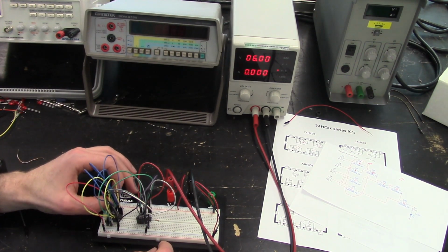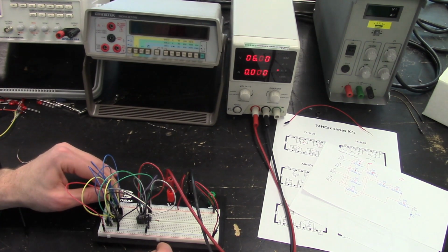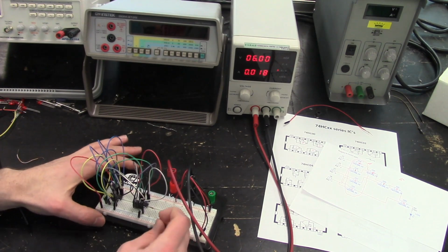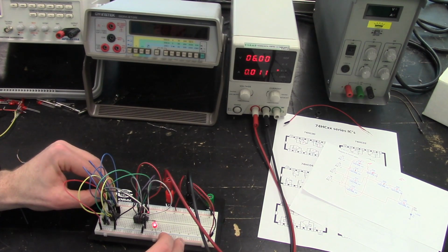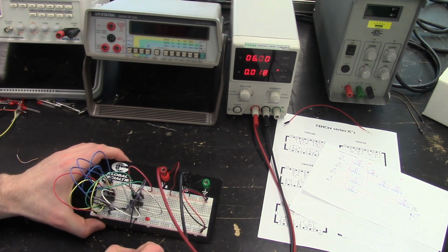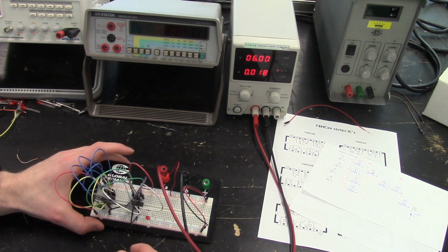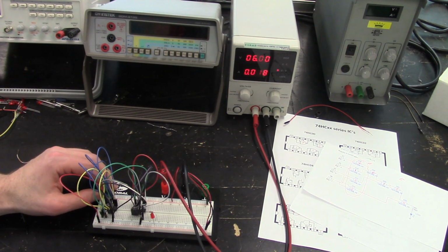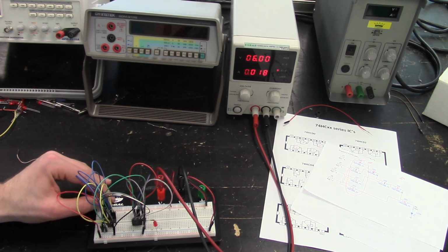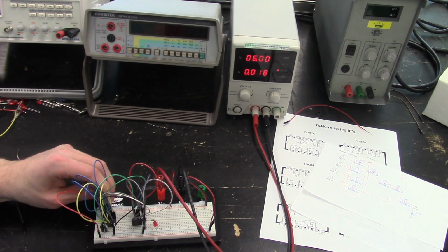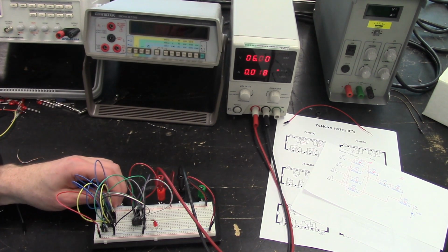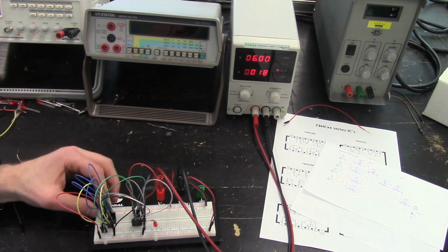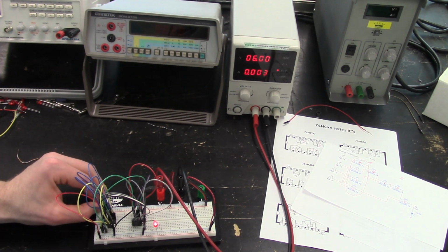But one thing you can do to check is switch around the inputs. So in particular, when we have an output that's supposed to be low, we'll put the LED back in to show that this is a low output as opposed to this high one. Interestingly, this particular circuit is drawing a different amount of current, in fact a lot more current, 18 milliamps according to the power supply, when we are outputting a low. And that's the same across a couple of different lows. So here's 8, and then we'll put it back, we'll go to 9. Whereas if we go up to 1, it goes back down.